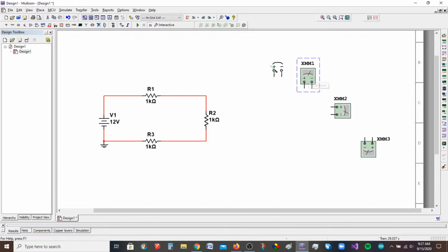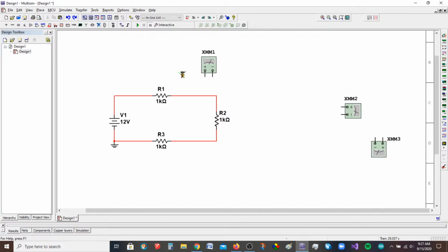So I'm going to put this multimeter as if I was using it as a regular ammeter. So we know that we have to break the circuit. Now in this little series circuit here, I can do that anywhere. I could do it right here. I could delete it, and I could insert my ammeter in its place. Okay, Control Z, Control Z. It will undo up to 10 commands, by the way, if you want to use Control Z.